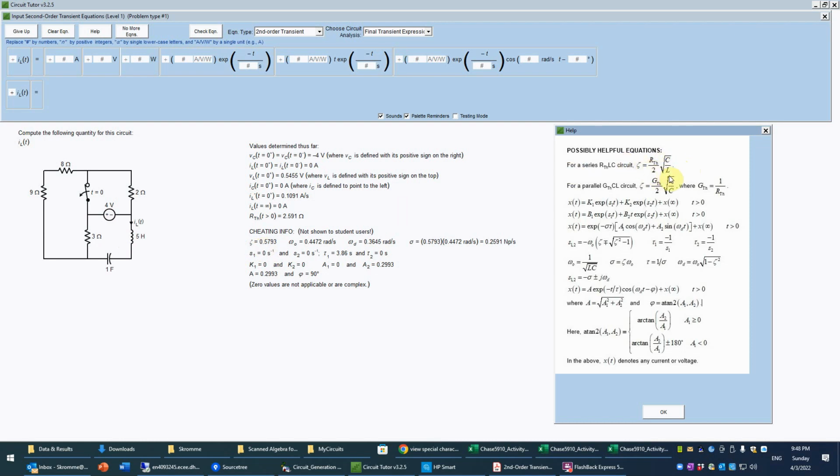And you should also check that this is in fact dimensionless, as shown here, because an ohm times a square root of a farad over henry, that does work out, as shown in the introductory tutorial, for example, to be a simple dimensionless, or 1. Okay, so based on the fact we're underdamped, well, we can now choose the form of the transient solution. It has to be this. And we could also go ahead and put in the units. It's basically choosing one term here for units that are either current, voltage, or power. So we're going to enter it because we know it's a current. This has to have units of amperes.